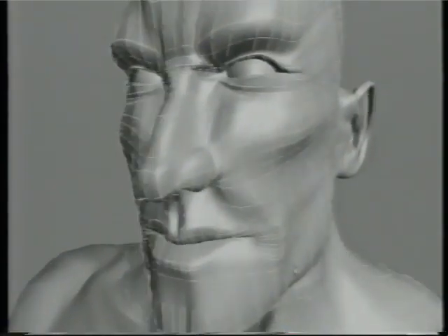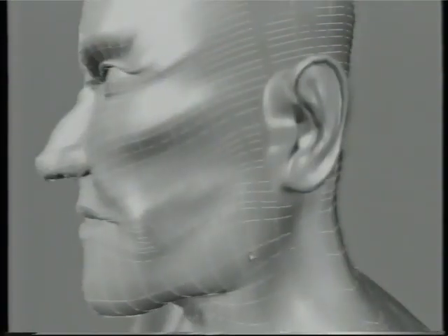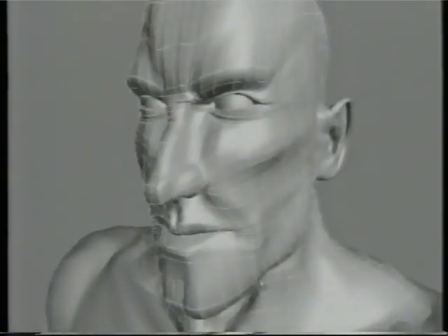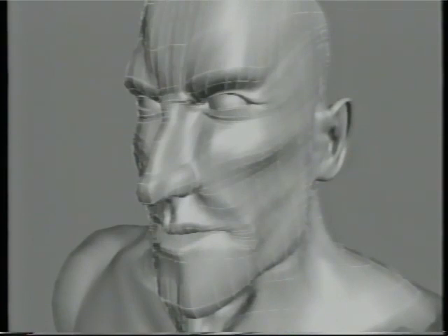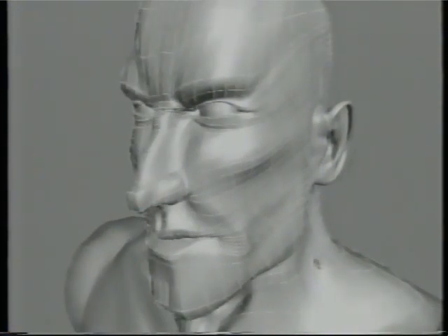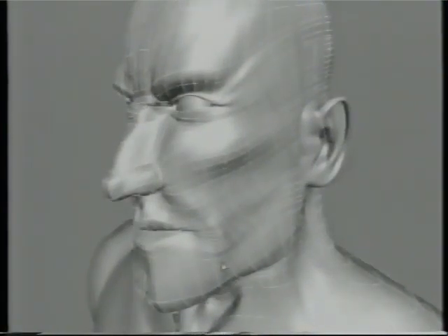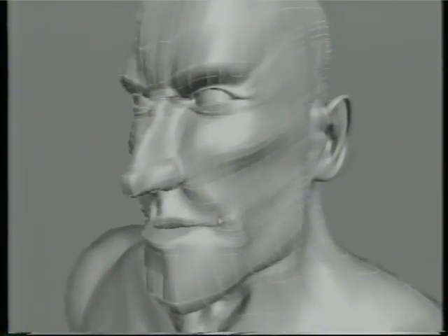This has some advantages, this particular topology for heads. That is, the texturing works very well, because if you use UV maps and NURBS, then you won't be stuck with a topology that is radiating out from the mouth, and that becomes very difficult to texture map, because the texture has to also go in a radial pattern, since with NURBS the UV textures are built into the geometry. And the other nice thing is that the only surface connections are for the ear and for the neck. So this method works pretty well. The drawback is that it's difficult to model because there are so many points.